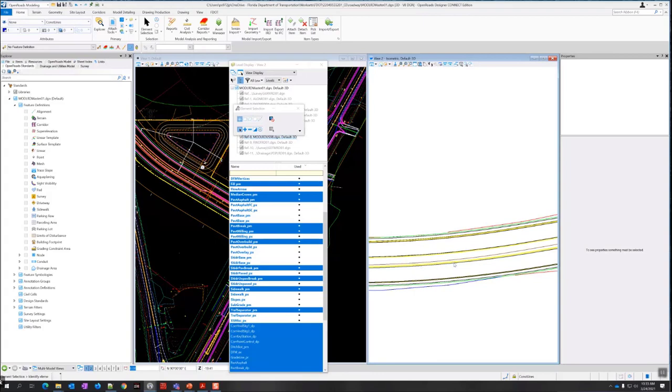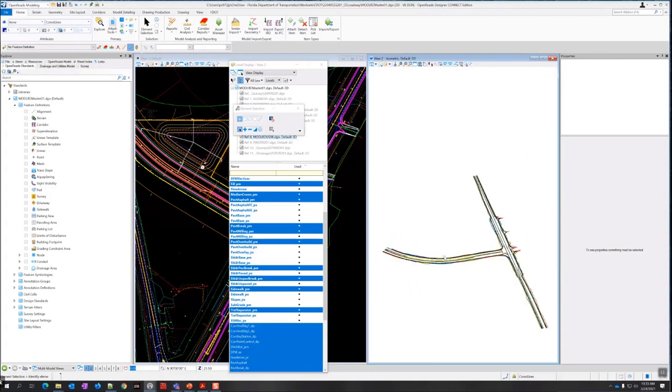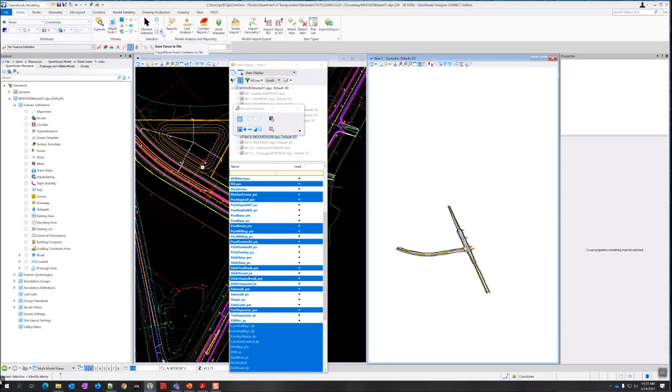So this one's ready. I think I have all my lines. We're simplifying it down, but we're simplifying it down in the 3D view, so it's just got to be straight 3D lines. I'm going to place a fence on here. Come back here to drop down on element selection, place fence. Make sure your 3D view is zoomed out enough to do this. Just place a fence around everything.